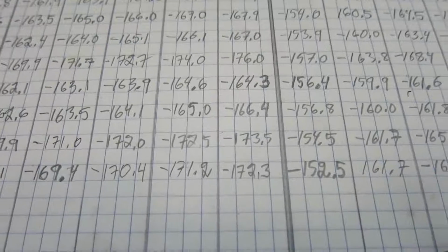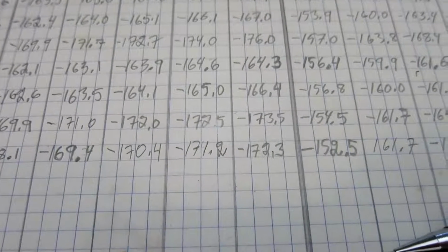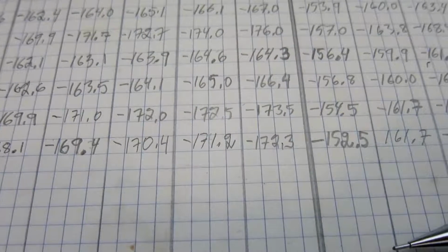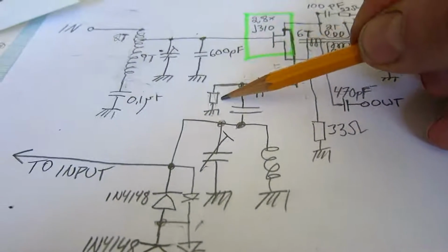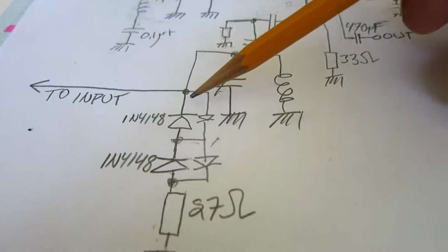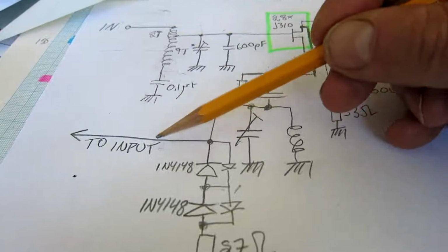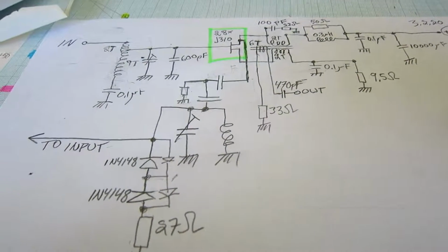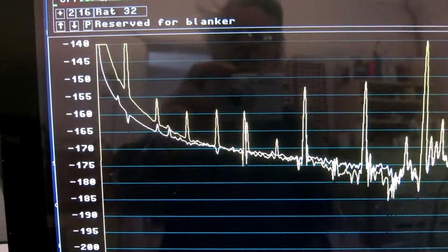There is positive feedback in this oscillator, as in all oscillators. Small variations in the amplitude might be amplified, which points to an insufficient limitation in the crossed diodes used for amplitude stabilization. I have removed this resistor here and also shorted this resistor. This makes the limiting a little bit harder by these diodes. I mean, the transfer curve from amplitude here to amplitude here becomes sharper like that rather than like so. As a result, the amplitude is a little bit lower. And indeed, that makes a small difference.